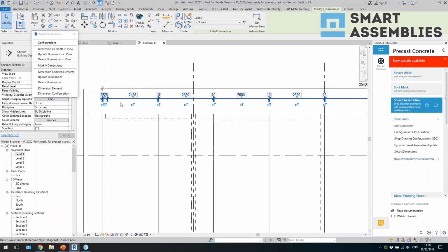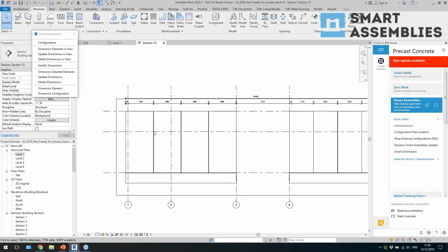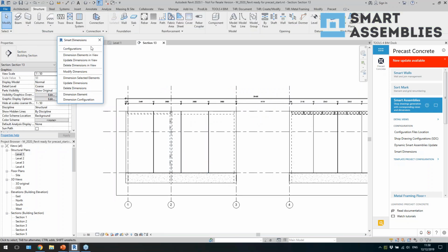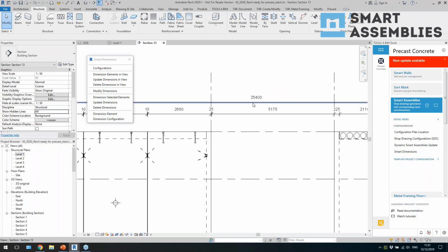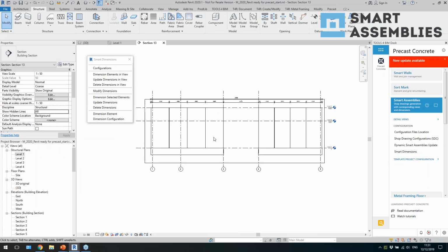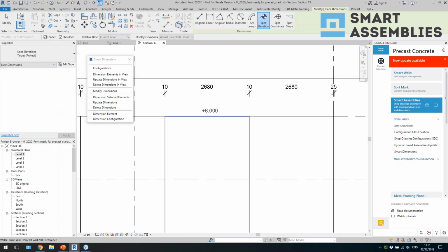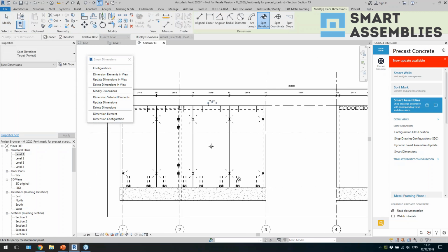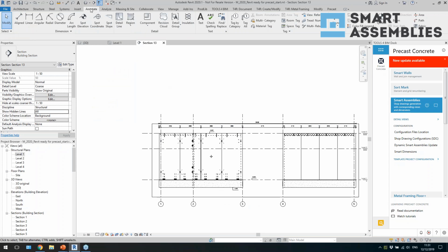So now we'll see that I have this dimension line, which is giving me dimension lines of the panels. So in this case, I was measuring panels, but it could be, I don't know, structural connections or something, and then maybe I'll just change visibility so the connections would be visible. And this one was measuring actually this wall, but so I could filter out that as well. So this kind of stuff, right? And then you just tweak it with Revit, right? You just go on, move, add some information and so on, like that.